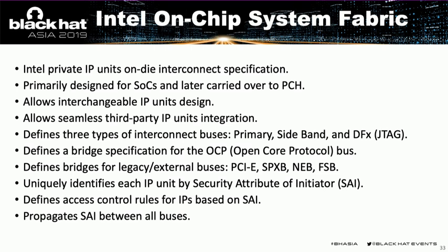IOSF is a private Intel on-die interconnect specification, primarily designed for SOCs but later extended to PCH. It allows Intel to seamlessly integrate third-party IP units and interchange the logic between various models of the chips.